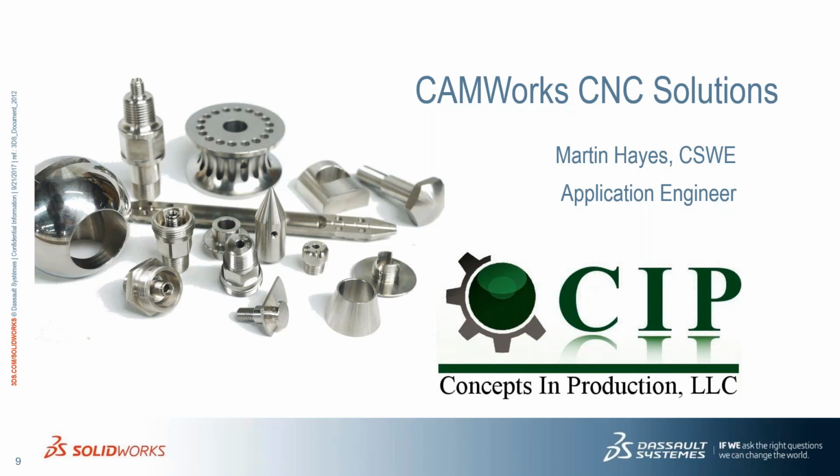From there, we're working in the 3D environment rather than working with just chains of toolpath code. That is able to give us a simulation of the part being cut itself, which is like a digital dry run of the parts, allowing us to save time on the floor running the parts, as well as save scrap cost, avoiding gouges, avoiding running parts that have mistakes on them.